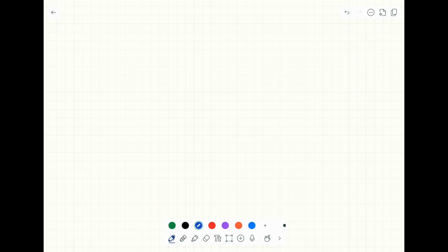For the power triangle, we always draw the baseline as the real power, the power delivered to the resistor, and the vertical line represents any reactive element. It can be a capacitor, an inductor, or the combination of capacitor and inductor. And we put a Q here.